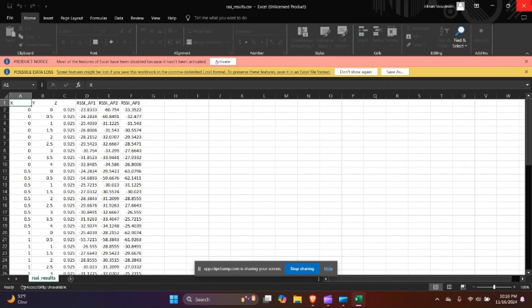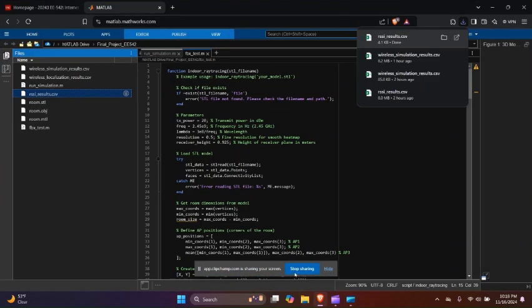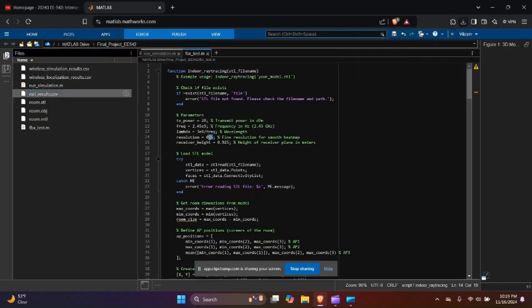Again, if you want more density, you can get an even more realistic map if you increase the positional density resolution. This 0.5 is very low. You should ideally do something like 0.01, and it will have a really fine, smooth heat map that is really indicative of a proper path loss map. This is just for a fast demonstration that I showed you this resolution.